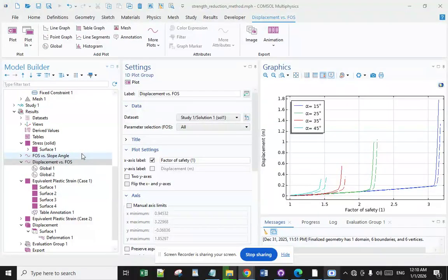This is helpful for oversight and reviewing on projects with various integrated components, as different components may have various design factors involved, and the margin calculation helps prevent confusion. For successful design, the realized safety factor must always equal or exceed the design safety factor so that the margin of safety is greater than or equal to 0.